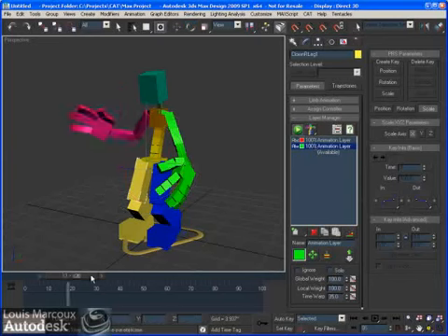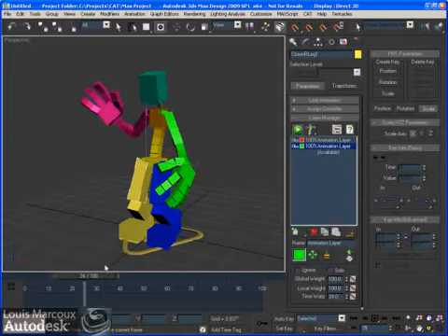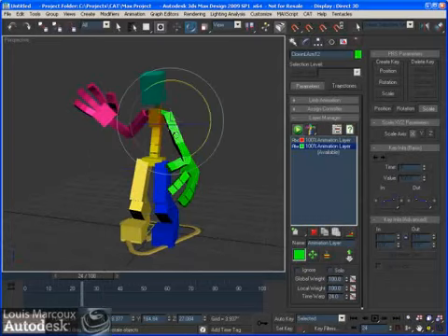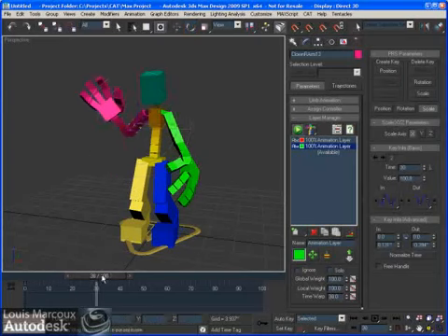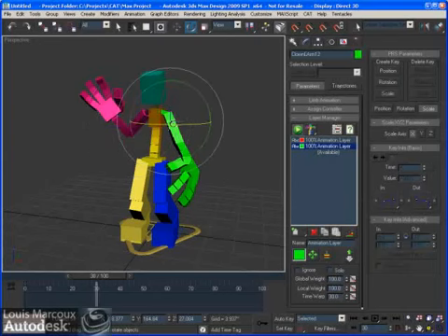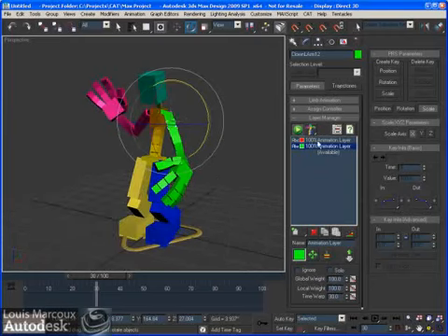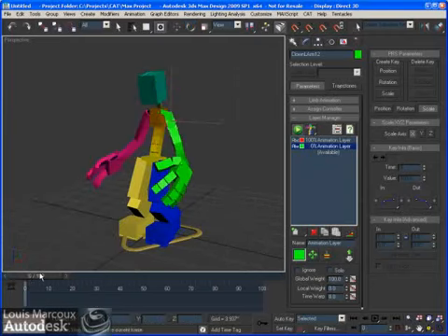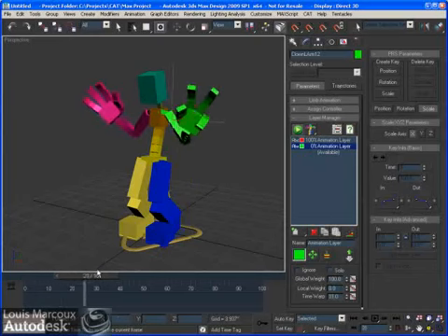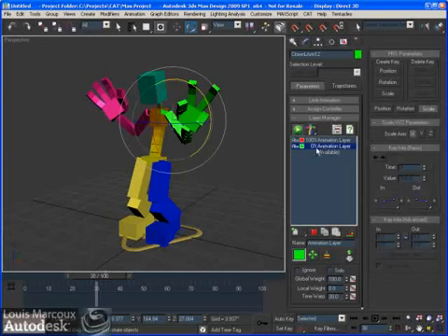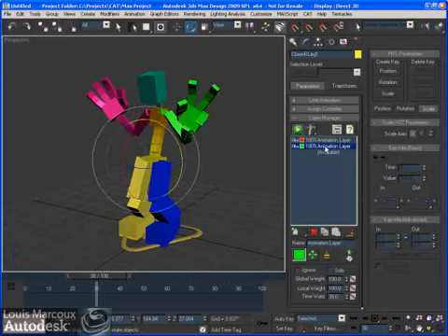But let's say I want the two animations playing at the same time and they're not affected by the same local group. This hand here is on a different local group, or local weight, than this one. So I can say I want this animation here to be 100%, but I'm going to grab the other end where I've created the other animation in layer number 1, and reduce the local weight of this one to 0. Now the two layers are playing at the same time. You see that the animation layer for this group is set to 0, but if I grab any other group like this one here, it's set to 100%. So I can continue to work on this animation here.